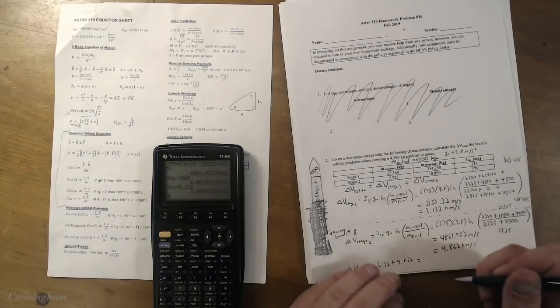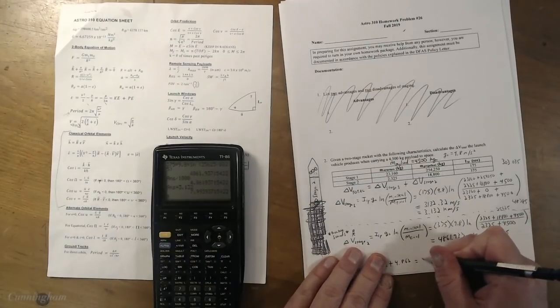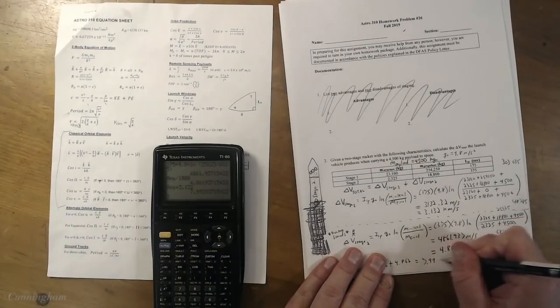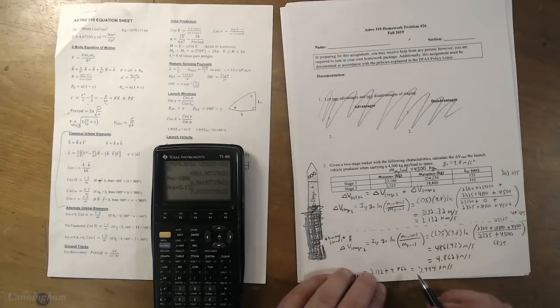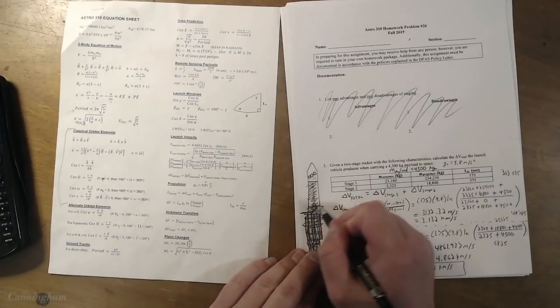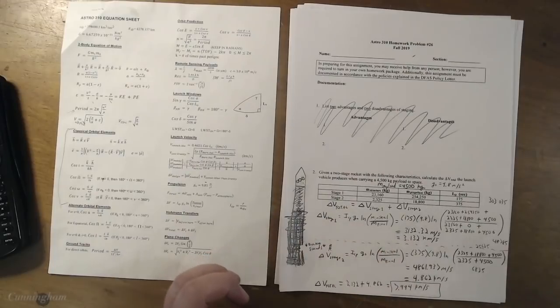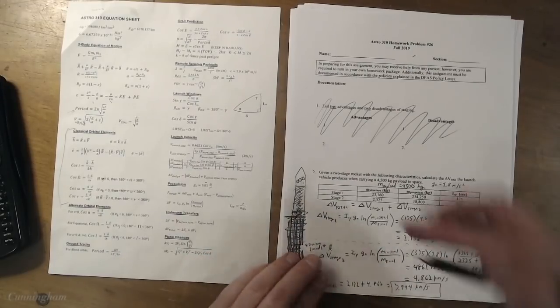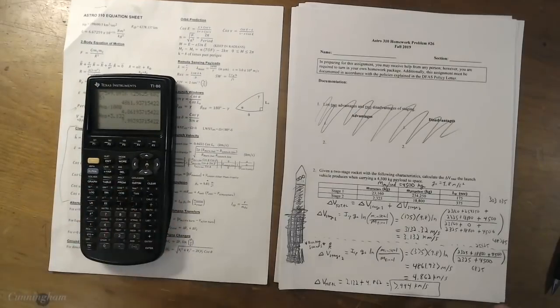Oof, I get that almost exactly equal to 8 kilometers per second, 7.994-ish kilometers per second. If you guys didn't carry rounding errors like I did, you might get almost 8. So, boom, between stage 1 and stage 2, after stage 2 burns through its fuel and then detaches, gets that satellite to orbit if it has at least 8 kilometers per second worth of boost in it. Ta-da! We did it. We launched our huge fat satellite to orbit. So, nicely done. We'll see you guys next time.